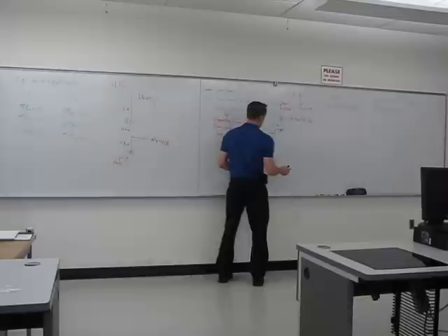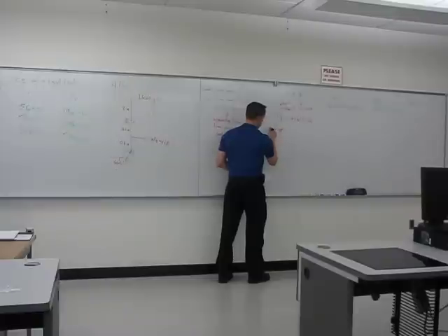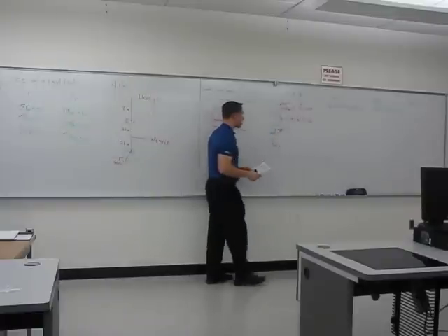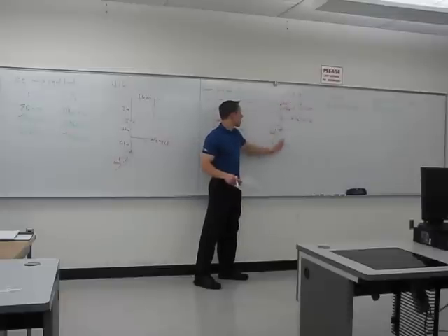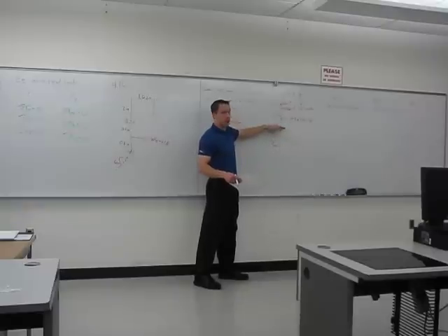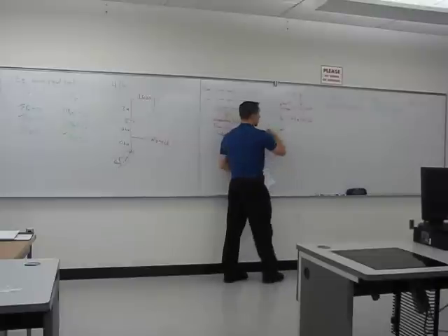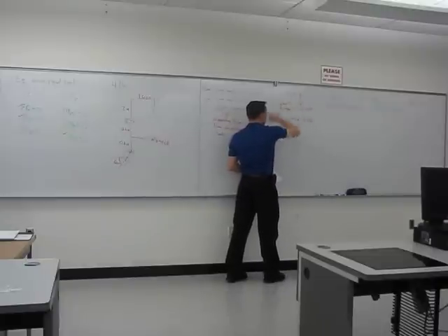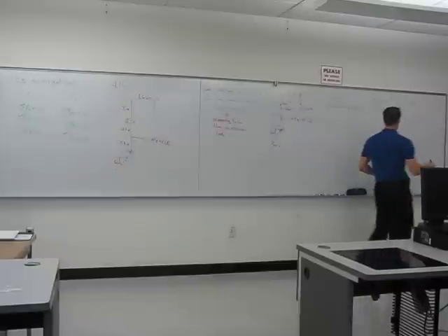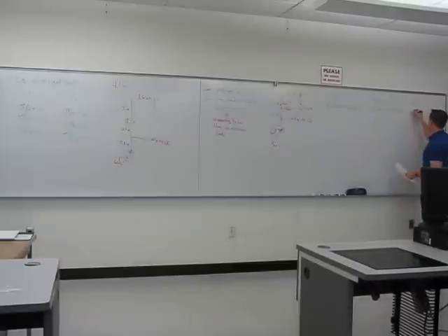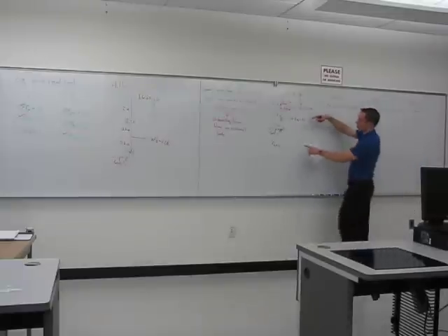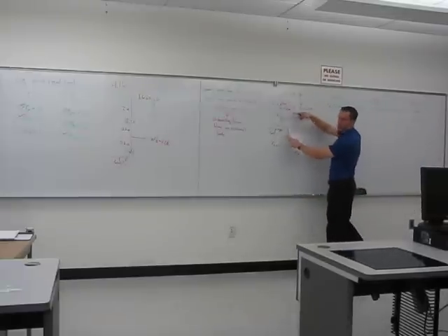All right, so let's see. Now remember the components for Fa over here. You've got a y component and an x component. Now the y component has a line of action that goes through C, so we don't have to worry about that one. But the x component, we're going to create some rotation around C. Hold the point C fixed and push to the right. That spins you in a counterclockwise kind of way. So we'll have a positive Fa cosine of 60. And the distance between A and C is 1.6 inches.